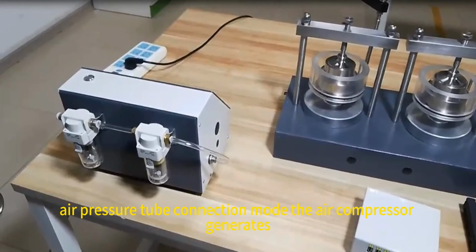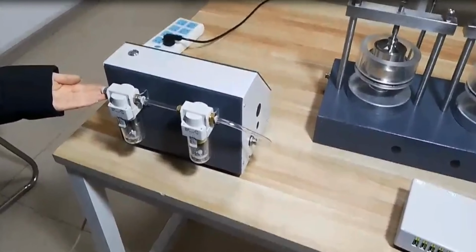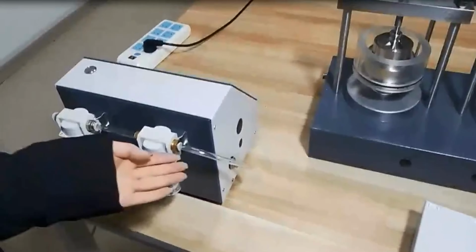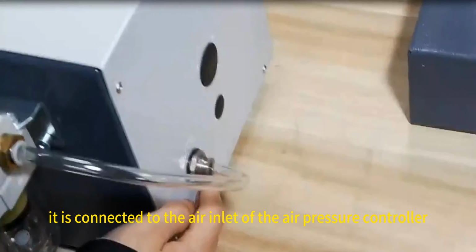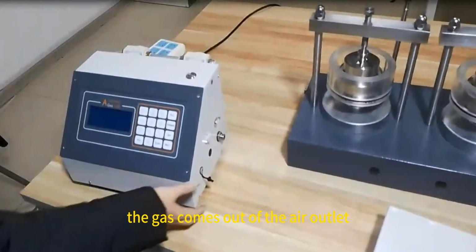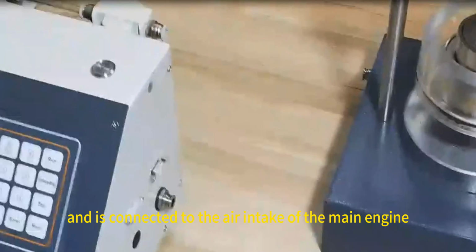The air compressor generates the air source, and the air source is connected to the air inlet of the filter. The air pressure tubes we use are all 8 by 5 millimeter tubes. After passing through the filter, it is connected to the air inlet of the air pressure controller. The gas comes out of the air outlet on the other side of the controller and is connected to the air intake of the main engine.